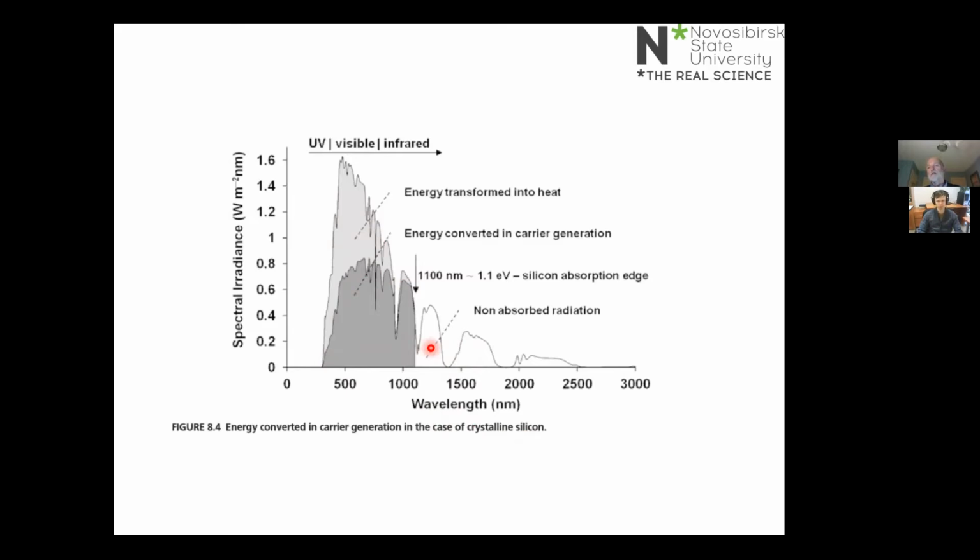Okay, we saw from the famous NREL chart yesterday that the relatively high efficiency PV technologies are the ones that have multiple layers in the PV cell. And what those multiple layers do is actually work on different bands of wavelength. So if we could combine a silicon layer with a layer of another material that could accept higher wavelengths, then clearly we're likely to get an improvement in efficiency.